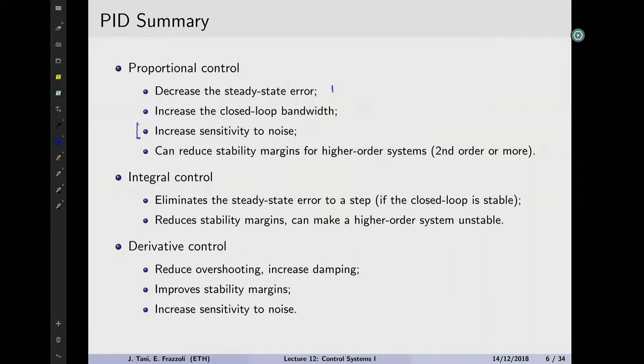Well, that constant tracking error will remain in memory, and eventually the controller will do something about it. So, adding an integral part to the control tends to make the transient response worse because you're keeping track of a history, but at the same time, it helps to achieve better zero steady state errors.